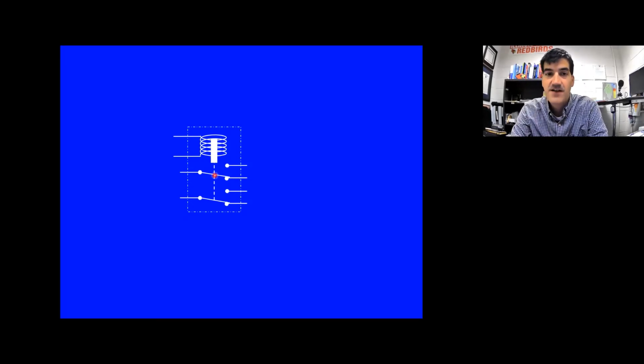So let me stop right here and ask you, how many connections or terminals or pins are there on a relay? A standard, and this is a pretty standard, double pole, double throw relay. Well, all you really have to do is count them up. So how many places are there for wires to connect? So you already know that there are 2 possible inputs or commons. You already know that there are 2 normally open, and this is shown as a normally open, and this is a normally open. There are 2 normally closed connections right here and right here.